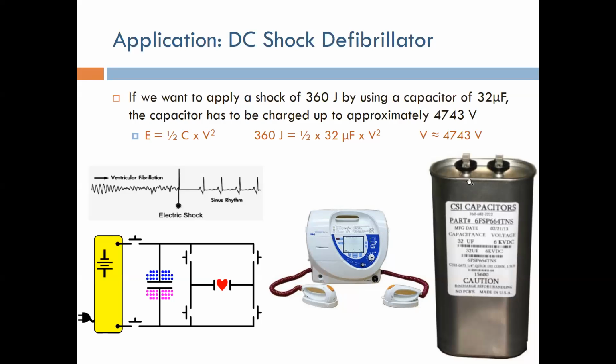Actually, this device should be charged at all times because this is an emergency device. You don't want to have to wait for the capacitor to charge while the patient is having a heart attack, okay? You want to treat the patient as soon as possible. So this should be plugged in at all times, and the capacitor is usually charged at all times.